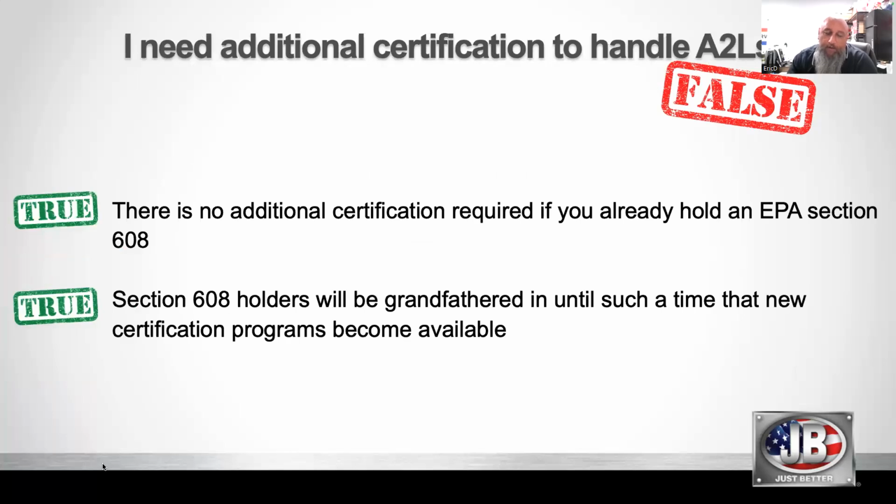Yeah, real quick, Tom. One of the things I like to tell folks is, when you get down to it, the new A2Ls are slightly, moderately, however they want to define it, flammable. They're not propane. They're not fuel, right? They are, however, slightly more flammable than what we're used to. And so that's where we want to do our due diligence, get our processes and our tooling and everything in line with the recommendations and requirements for this stuff, just so that we stay safe and our customers stay safe. Yeah, exactly.